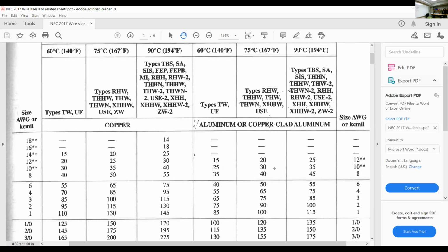And the insulation can actually make that overall size be fatter, to be bigger, because it's thicker insulation. So if you see two pieces of number 14, and you know one of them is bigger than the other one, it's not the copper that makes the difference, it's actually the insulator that does. It's either thicker or thinner. And it goes the same all the way down, no matter what size you're at. If you got better insulation, you're allowed to go higher on amps.